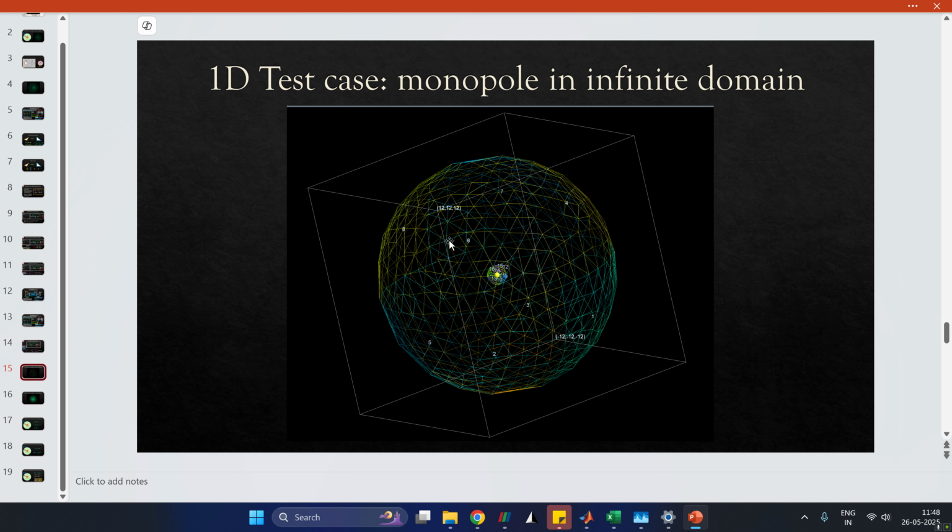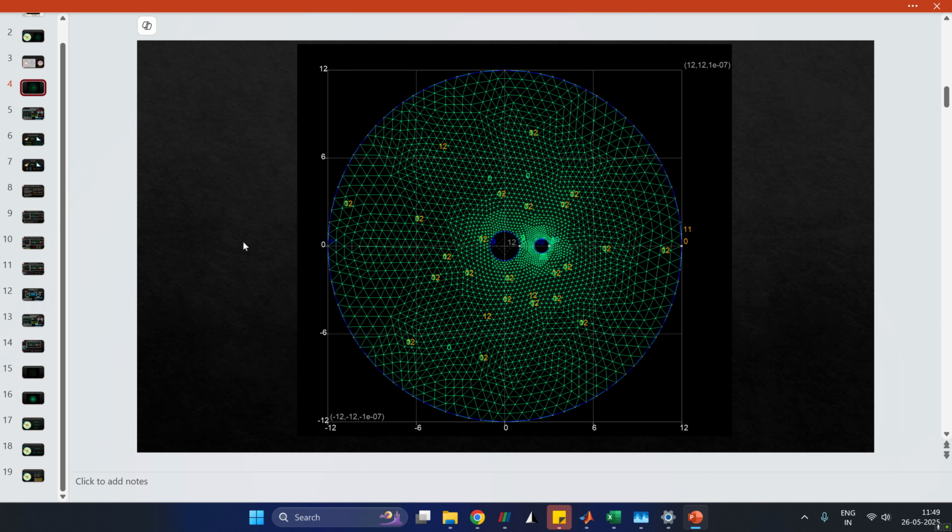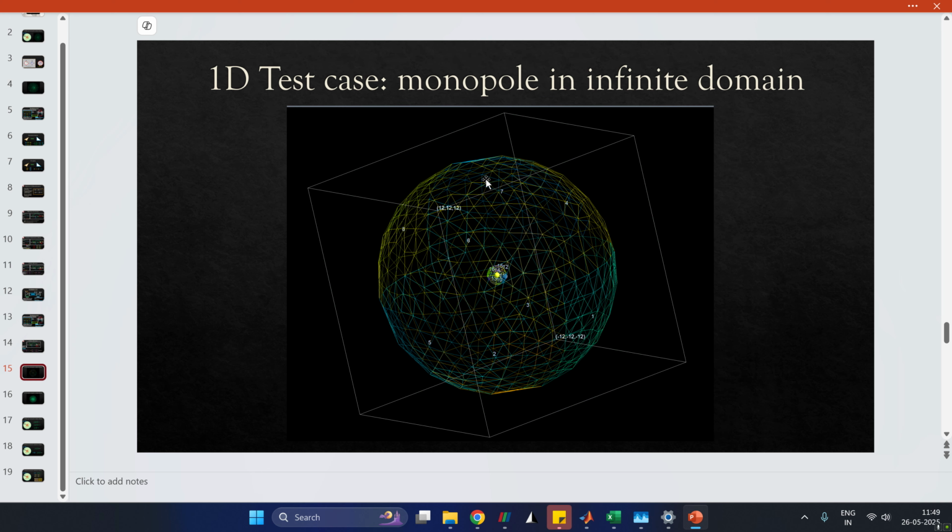And for doing that, we need again the 6-point Gauss rule on the triangle once again. So the same 2D analogy which we applied inside the triangular mesh, now we just apply on the triangular mesh on the surface, right? The Dirichlet condition imposition at the inner boundaries is just a strong imposition, so that will be very similar. So that is the analogy.